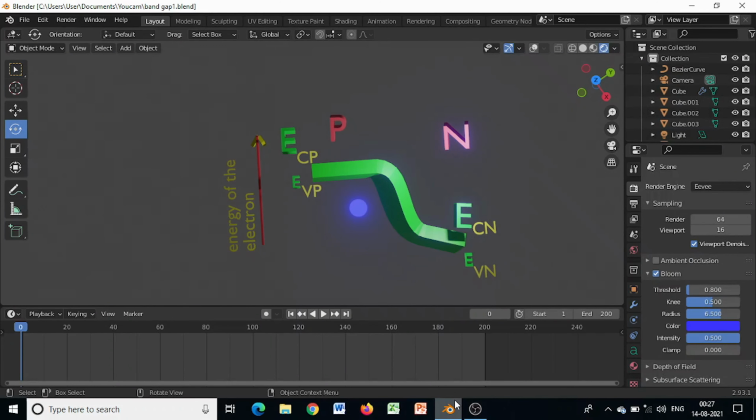In this energy band diagram, we plot the energy of an electron, which has a negative charge. Due to charge transfer, the p side acquires a negative charge, and for this the p bands are slightly raised relative to the n bands. Clearly, in equilibrium, the conduction band edge ECP in the p side will be at a higher level than the conduction band edge ECN in the n side.